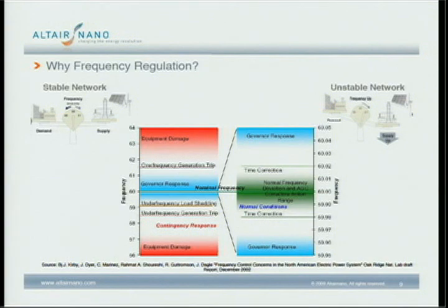And that's going on right now, 24 hours a day, 365 days out of the year. Generators are being brought up or down, just balancing out the system. And on a smaller microgrid, even outside of these control areas, generators are doing that with their own regulators, right? Their own governor response and their own regulation, looking at power output.